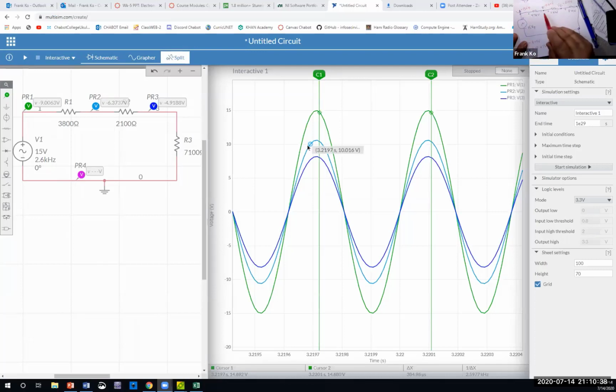our exercise in circuit G last week. And knowing what voltages we expect at specific points, our reference is ground. All we have to do is keep our black probe at ground and just move our red probe from here to here to here, which on our oscilloscope, we did this way.